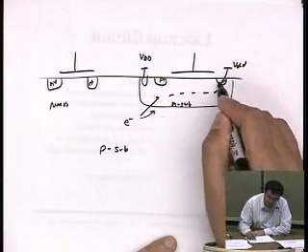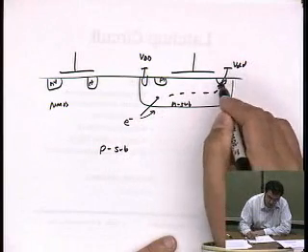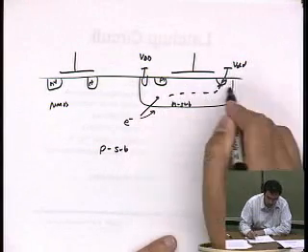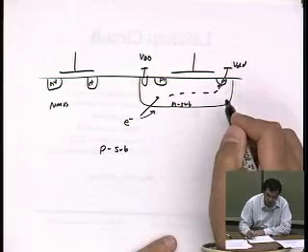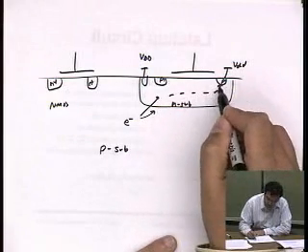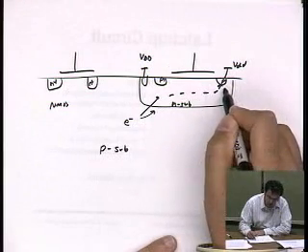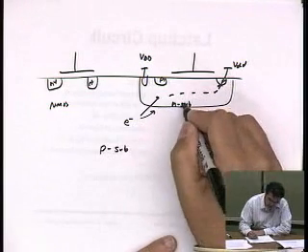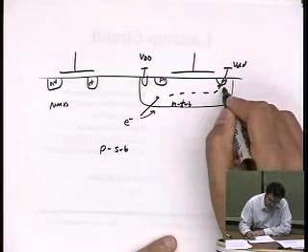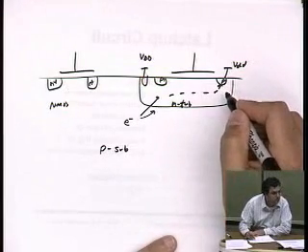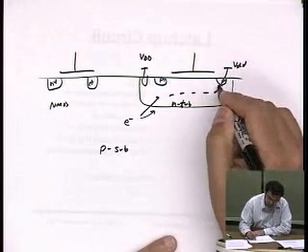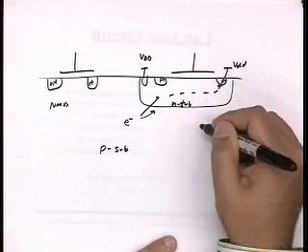And because this is held constant by VDD, most of that voltage drop is going to occur in the well. So the act of this electron traveling across here will charge the N tub a little bit negatively, right? Which tends to forward bias this junction just a little bit, right?